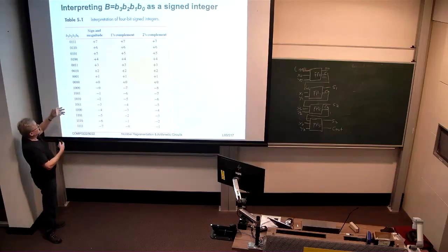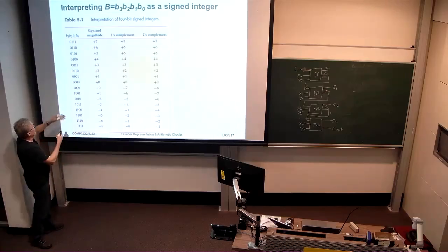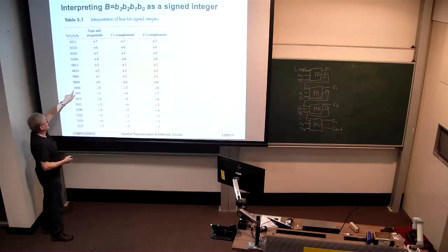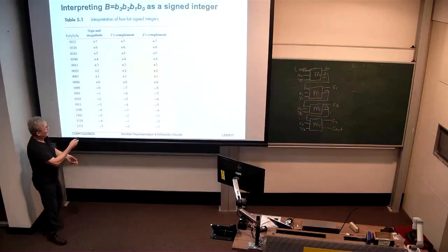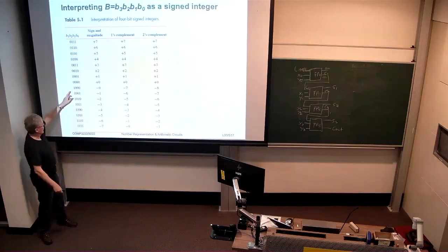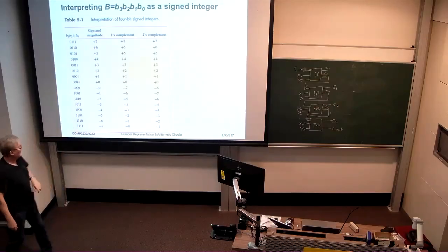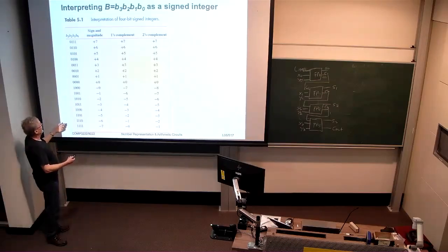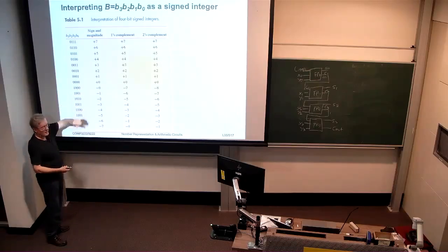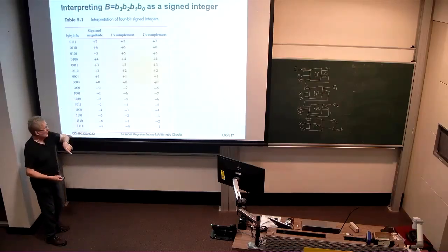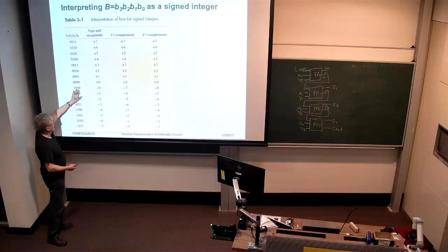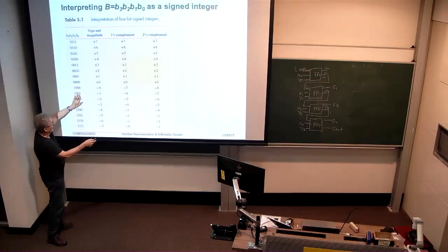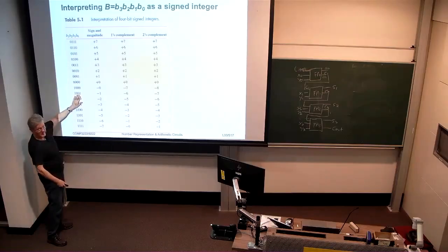1's complement, you have to complement every bit. So what's this number? Well, it's 0, 1, 1, 1. So it's 7. So it's negative 7 that 1, 0, 0, 0 corresponds to, and so on. To derive negative 7 in 2's complement, though, we have to take that value and add 1 to it. So it becomes this. So that's my minus 7 in 2's complement, right?